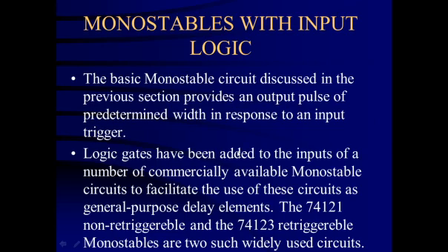The logic gates have been added to the input of a number of commercially available monostable circuits to facilitate the use of this circuit as a general purpose delay element. The 74121 non-retriggerable and 74123 retriggerable monostable are two such widely used circuits.